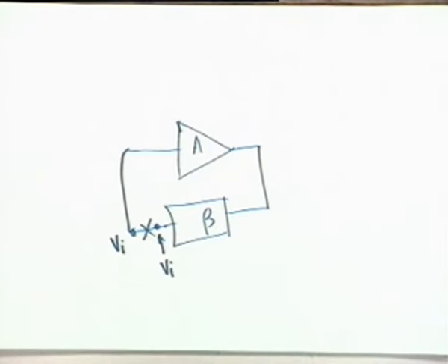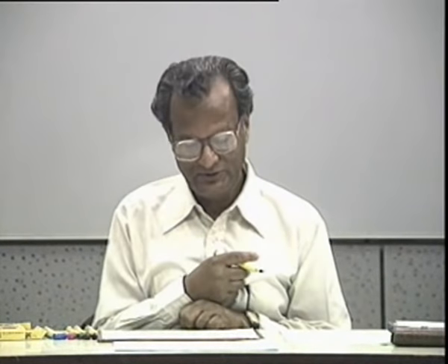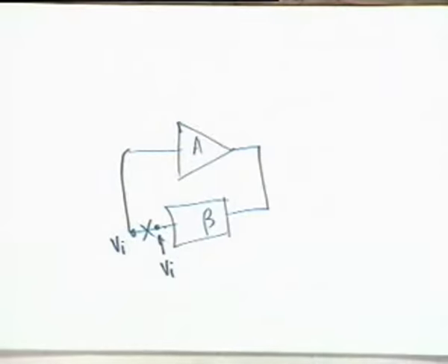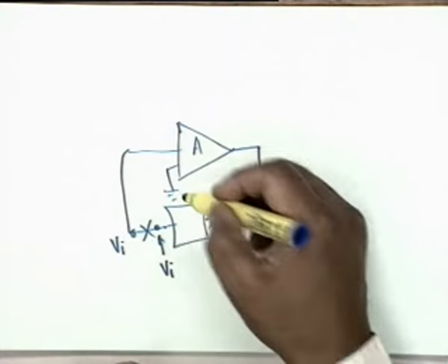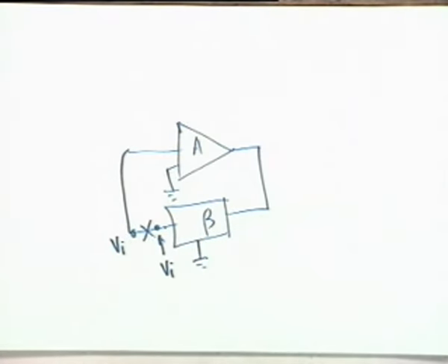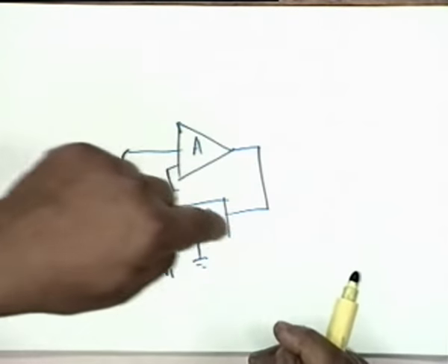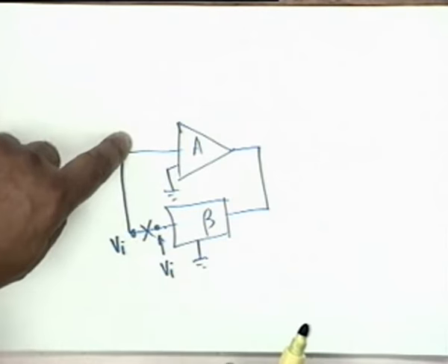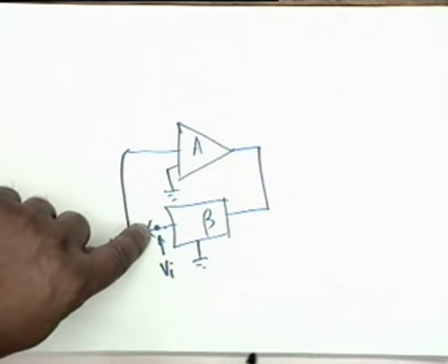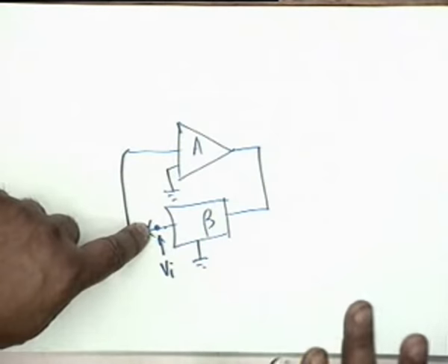Is the point clear? So is it not like splitting that short circuit wire into two parts? No short circuit. I have shown it by a block diagram. You see that wire joining A and beta circuit. Yes, that wire splitting into two ports that goes across A and beta. Oh, you see, there is another point which is grounded. The beta network is also grounded. Whatever the connection is from output to input, you break the connection at the amplifier input. You break the loop.